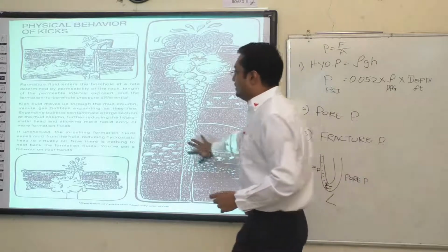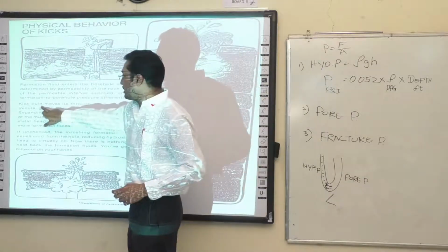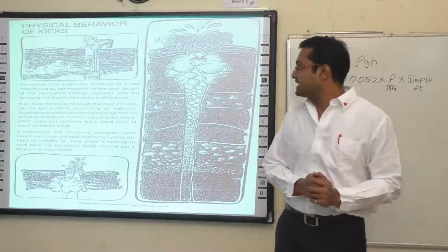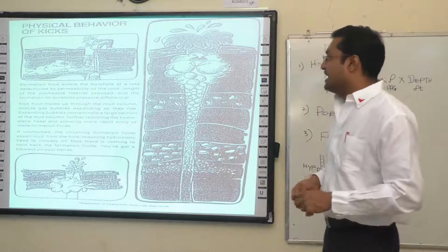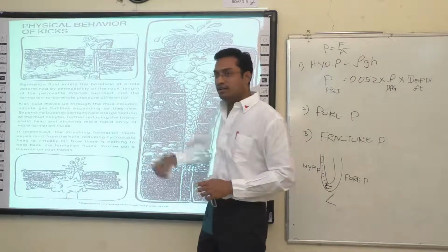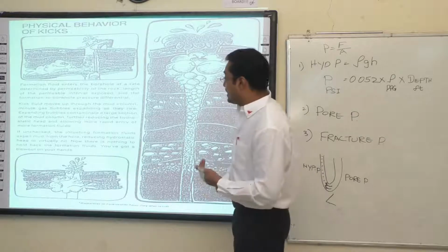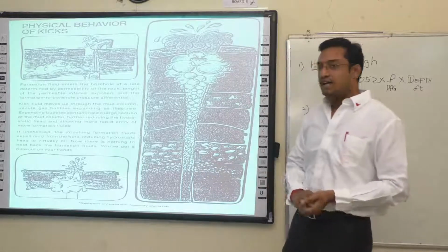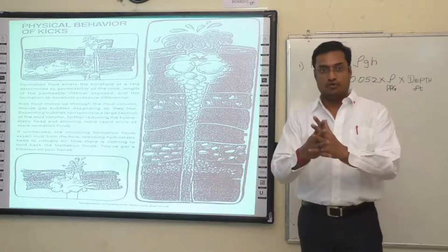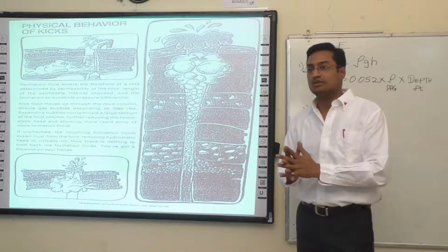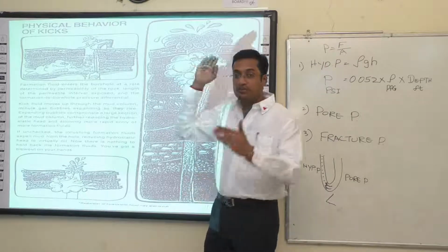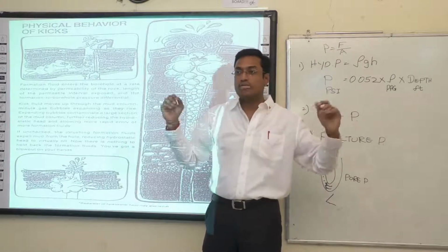That is this. So our kick fluid moves up through the mud column. Minute gas bubbles expanding as they rise. Expanding bubbles contaminate a large section of mud column, thereby further reducing the hydrostatic head and allowing more rapid entry of formation fluids. So it aggravates the situation. So this should not be allowed. So you have to stop. You have to put a check. So you have to close the well.